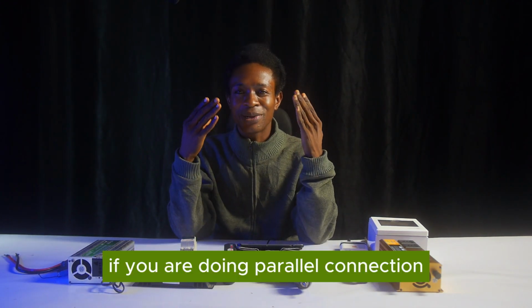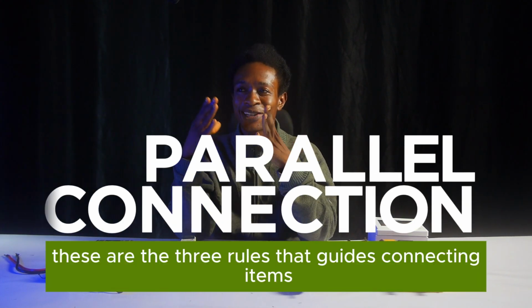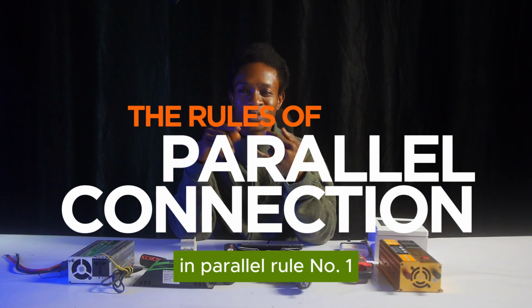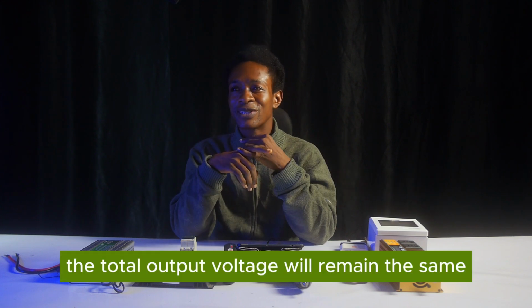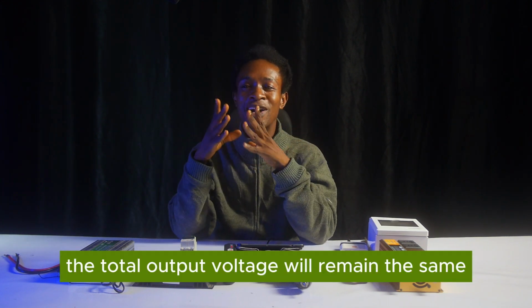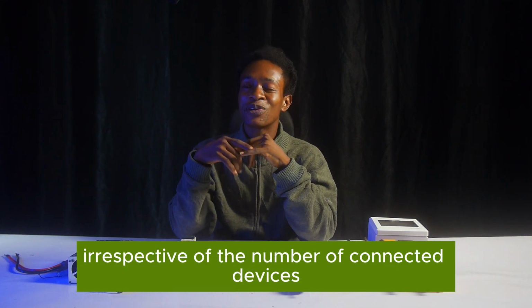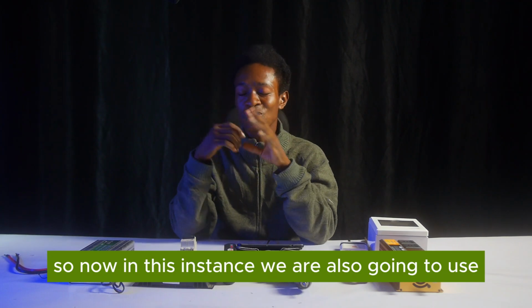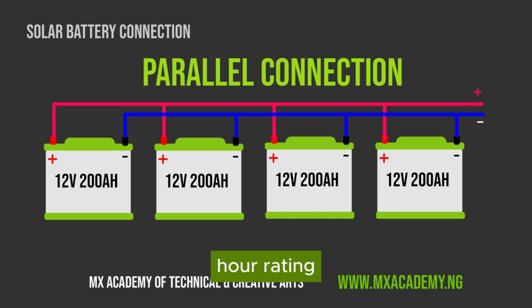If you are doing parallel connection, if you are working on a parallel circuit, these are the 3 rules that guide connecting items in parallel. Rule number 1, the total output voltage will remain the same irrespective of the number of connected devices. In this instance, we are also going to use 4 units of 12 volts battery with a 200 amp hour rating.